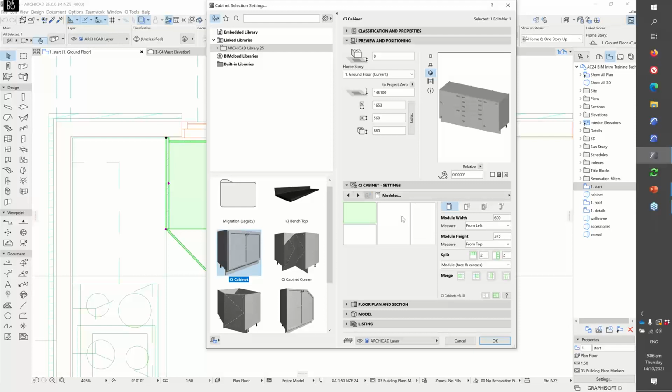So that should be helpful for those of you who prefer to set them out that way, or, as I have seen in a lot of cases, people like to draw them up in 3D and put their partitions in by eye to get everything looking the way that they want it to. Then you'll be able to jump into the settings here and make them into actual sensible numbers, so that it makes a more sensible cabinet with nice round numbers like 600 instead of 597 and that sort of thing.